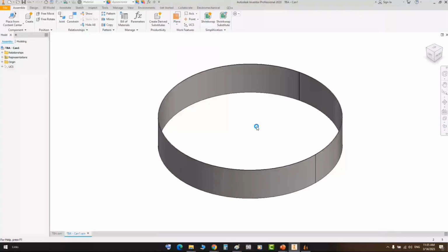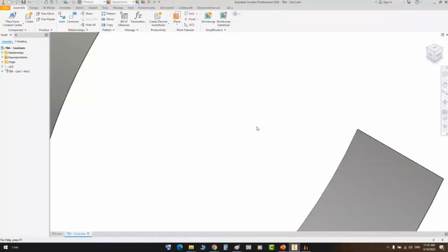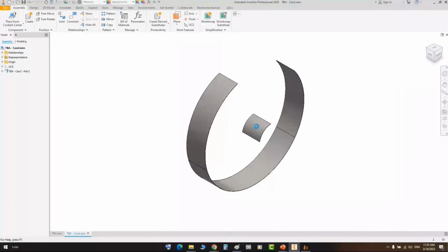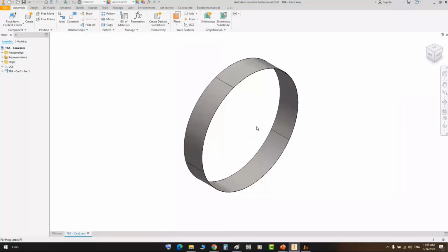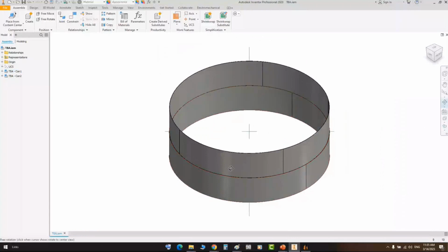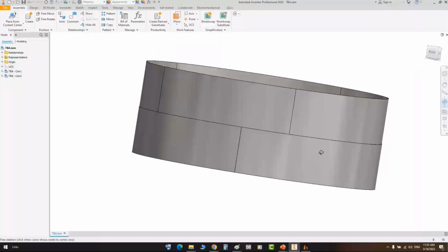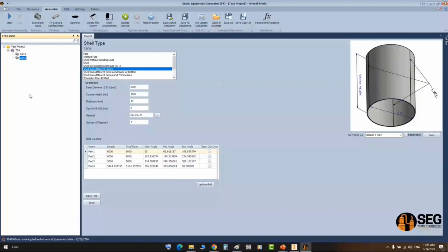that's the first course, including 3 blades. And the second one, we defined it as a shell from different pieces, and we defined each blade length. After creating it and assembling it to the final assembly of the equipment, you will get different longitudinal welding line orientations. And for this form, when you select that, you can see the start angle for the first longitudinal welding line.